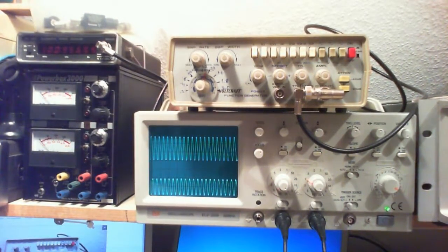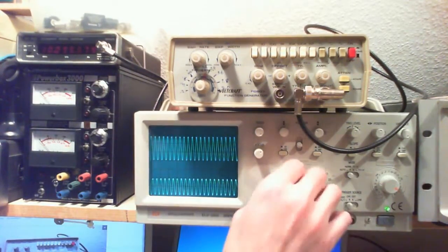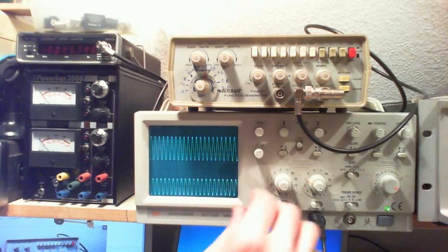Basically we had 3 phases over here: the output voltage was decreasing all the way up to 563 kilohertz. From 563 kilohertz all the way to 4.7 megahertz, the voltage was increasing all the way to 11 volts, and then from there the voltage was decreasing again. So we can go between these three phases and see what the signal is doing.